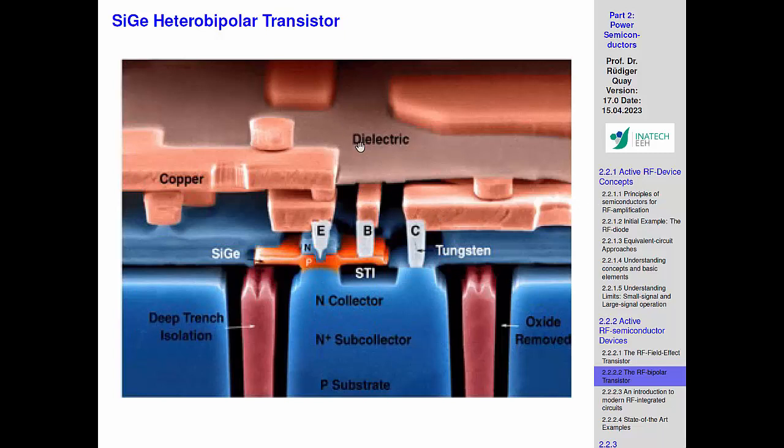You don't have to know much, you see that. You see also that we need to connect the emitter with high current, but we don't want to build an additional emitter base capacitance, which would be an input capacitance. So we again put this in this direction and take this from the left. You see also this is a small device and a big chunk of copper, which helps to get a lot of current in and keep the resistances low. But we also do this very intelligently, so that we are not coupling too much. That's just to give you a little bit of flavor of how things can be done finally.